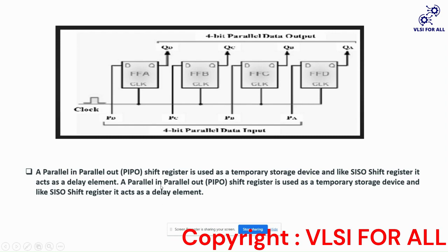The parallel input, parallel output shift register can be used as a temporary storage device. In a serial input, serial output shift register it acts as a delay element, whereas in a parallel input, parallel output shift register it is used as temporary storage, and it can also act as a delay element. Now let us go into the Verilog code of this parallel input, parallel output shift register.